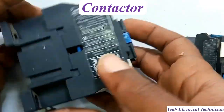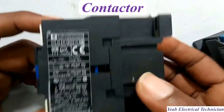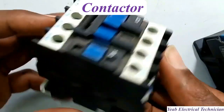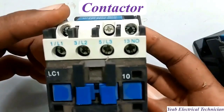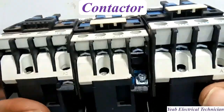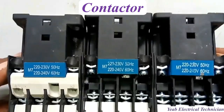Contactors are often used as motor starters, which connect or disconnect an electric motor from the power supply. They are used to switch large lighting installations on and off, especially in commercial and industrial settings. Contactors also control other equipment like heating elements, capacitor banks, and other large electrical loads.